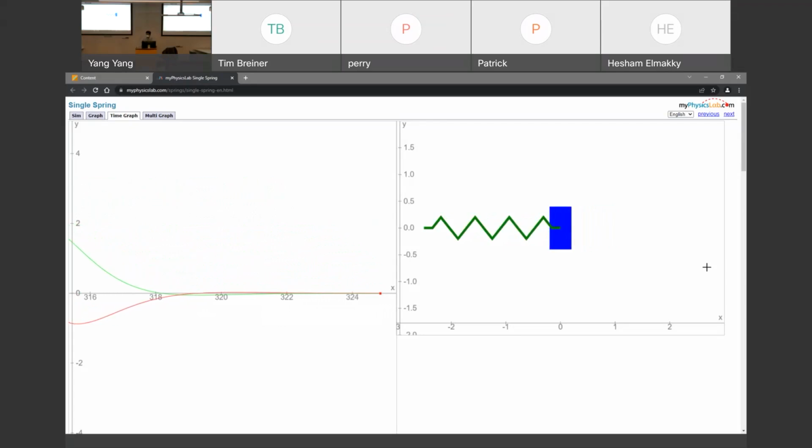The motion of the system decays very rapidly, similar to the critically damped system. For critically damped or overdamped systems, as you can see here, there is no periodic response, so we do not have to discuss natural frequency because there is no natural frequency here.